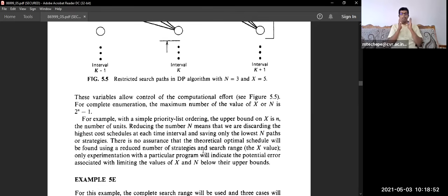That is the main objective function. You have to commit the least cost generators. If you simply choose the fifth generator, fourth generator and third generator, with this combination the cost of the power generation will automatically become higher. If the cost of the power generation becomes higher, then that is of no use. No need of running, because the cost goes like anything. Then what is the need of generating that power?